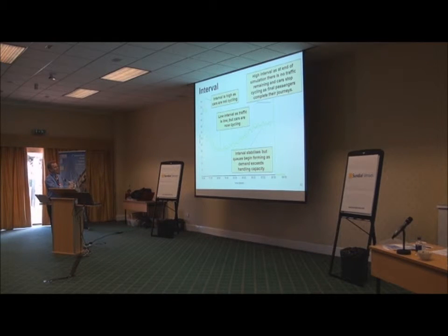Now, as demand goes up, we have a low interval because the cars are cycling, but they haven't got many stops, so the round trip time is quick. Then it comes up to this point where it gets to about 30 seconds, which is what we're expecting from the round-trip time calculation, and it stabilizes, because the system is working really well. It's dispatching a car every 30 seconds.